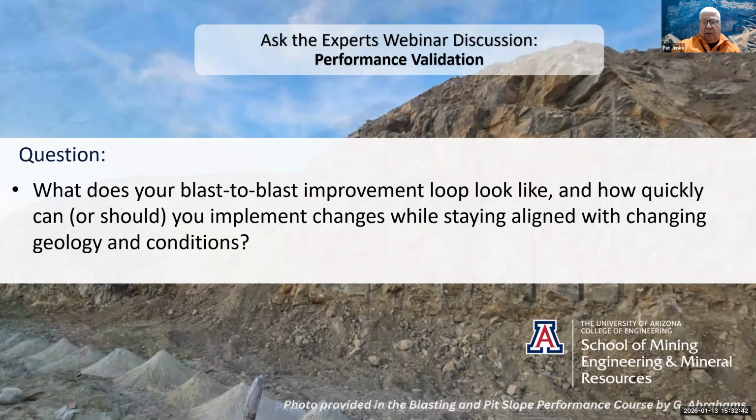Maybe our frequencies are not correct. Do we have undetonated holes that are causing oversize or excess confinement and adding to ground vibration issues? Are there any other observed performance issues that might be related to point of initiation, timing, firing sequence, or excessive confinement?